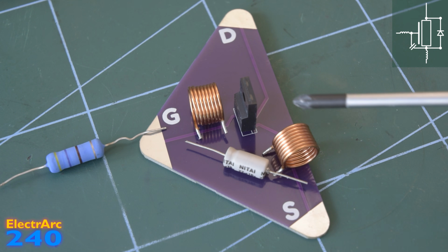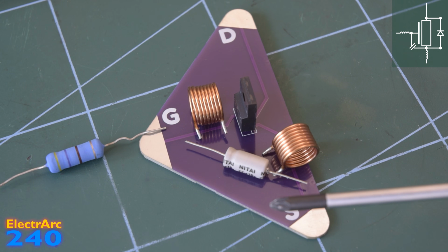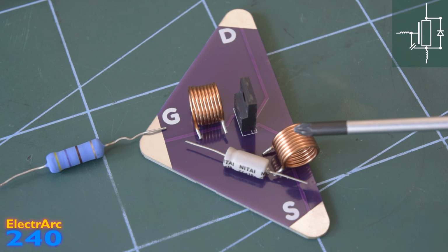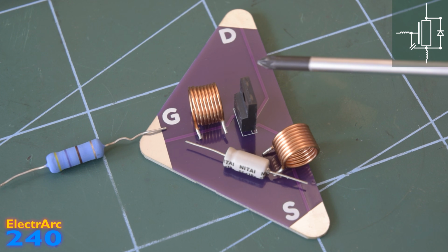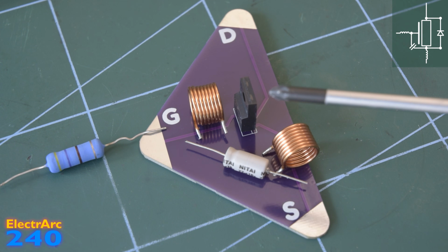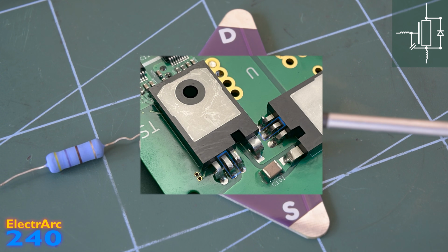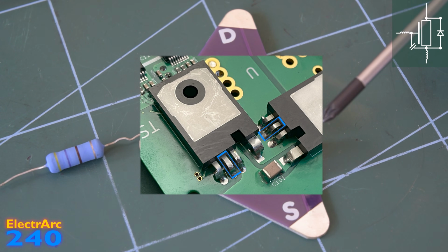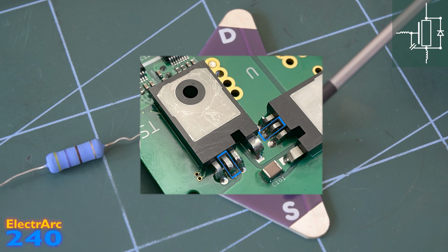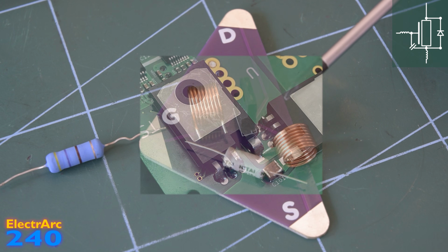And because the source inductance is still part of the gate drive circuit, or what's commonly referred to as the gate drive loop, the voltage generated by this inductance will actually appear on the gate, which can again turn on when you want it to be off, or turn off when you want it to be on. It's not good. The best way to mitigate against this is to use a MOSFET with a Kelvin source connection. This is a fourth pin, which is essentially a second source that you just use for driving the gate. This will almost entirely eliminate this issue, as long as the Kelvin source connection is actually made onto the silicon die and not just connected internally, which is what I'd call a fake Kelvin source.